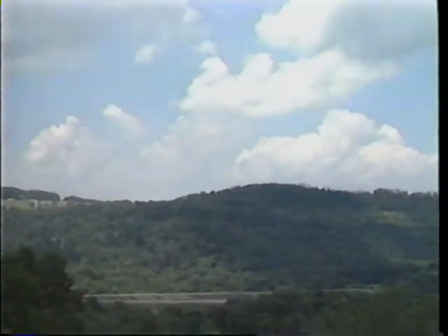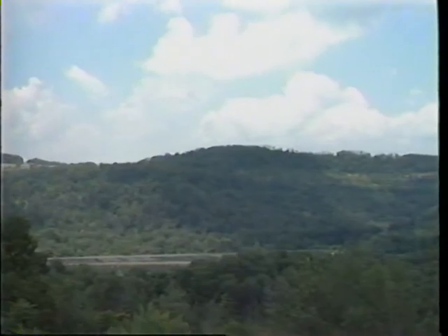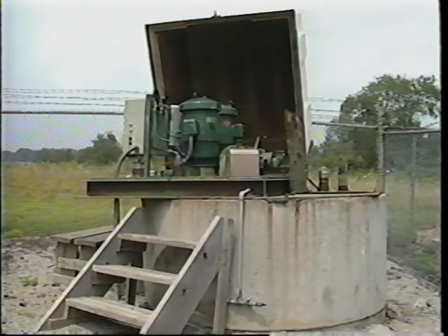Obviously, water cannot flow uphill. When sections of a sewer network are at a lower elevation than the treatment plant, or when hills and valleys are in the way, pump stations are needed to lift the wastewater to a higher point from where it can once again begin its downhill ride.